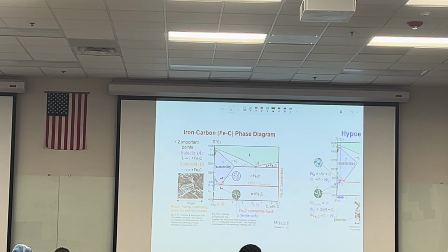You're going to have, for example, that much alpha and that much cementite phase. In total, in the question we had 2 kilograms. For example, if we end up with 1.5 kilograms of alpha, it means the rest is going to be cementite, half a kilogram. But some of that alpha is the eutectoid alpha, and some of it would be pro-eutectoid.